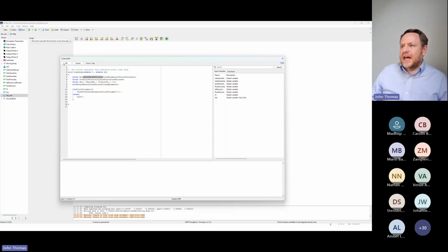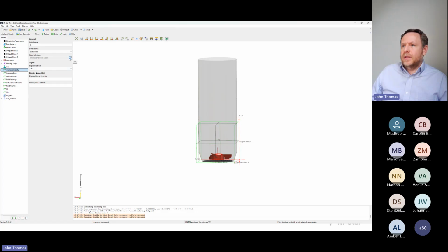And how am I doing interface velocity? That's just a global variable. I'm taking the mean of the interface velocity as we're directing the stats. Interface area, pulling it into the code. Tank diameter, that's the set value. Fluid viscosity, set to fluid viscosity. Diffusion coefficient, set to diffusion coefficient. Fluid volume, set to fluid volume. HL, HLA being calculated as part of the script.